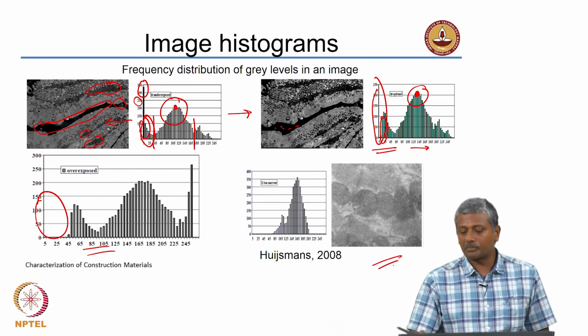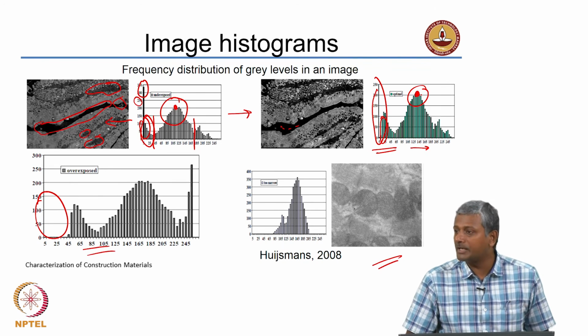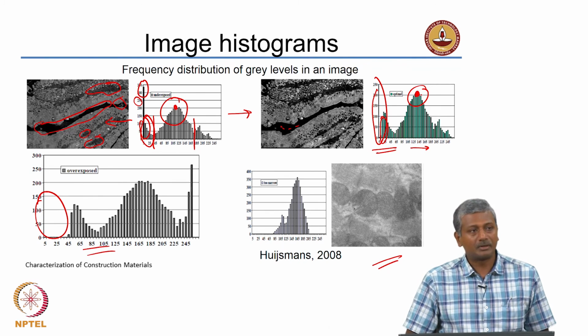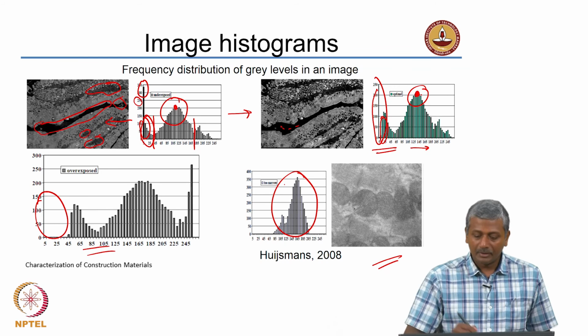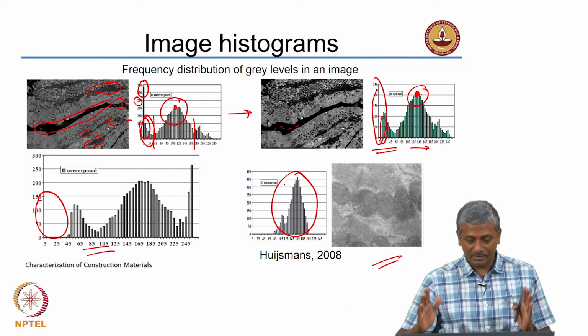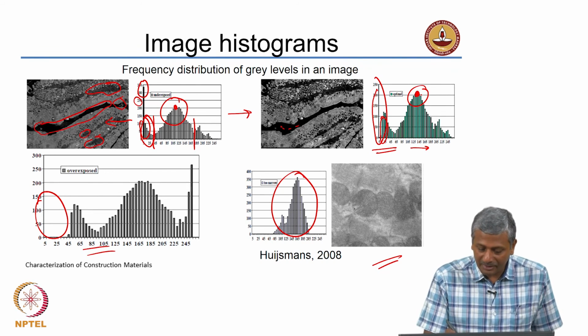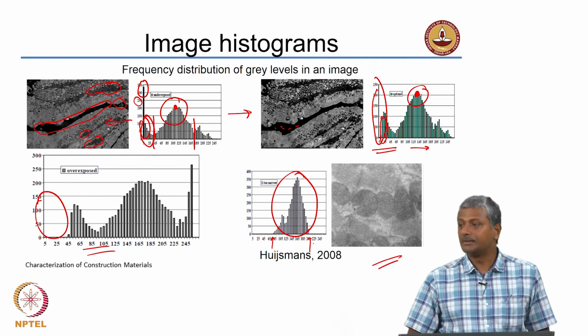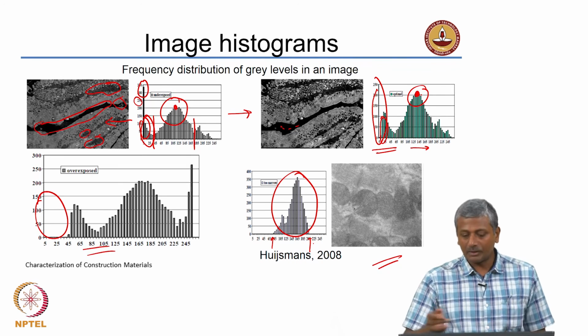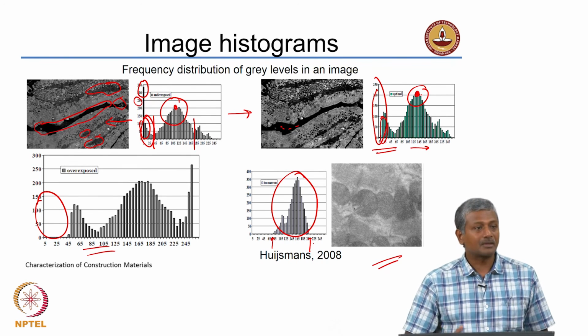This is again one more picture with more subtle gray levels. You do not really have a completely black or a completely white feature in this image, right. But you look at the distribution of the histogram, it is confined to somewhere at 80 to about 205 or 210. So, it is in a narrow region and your total image looks almost completely uniform.